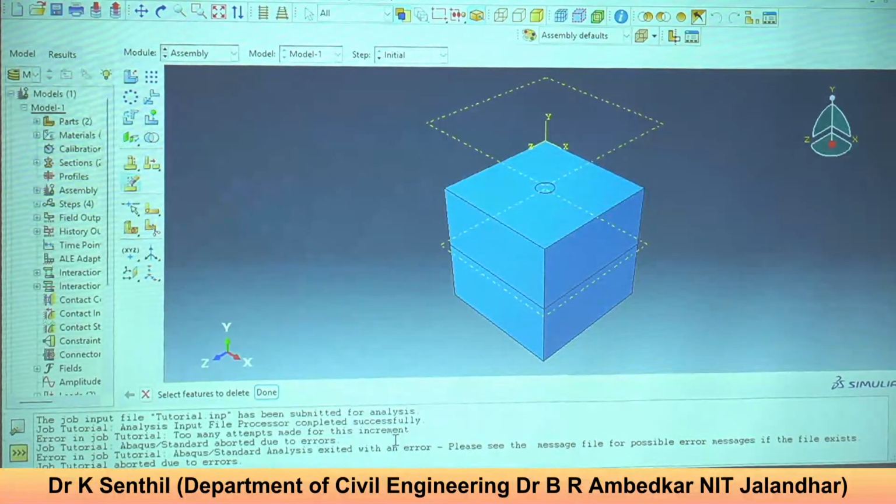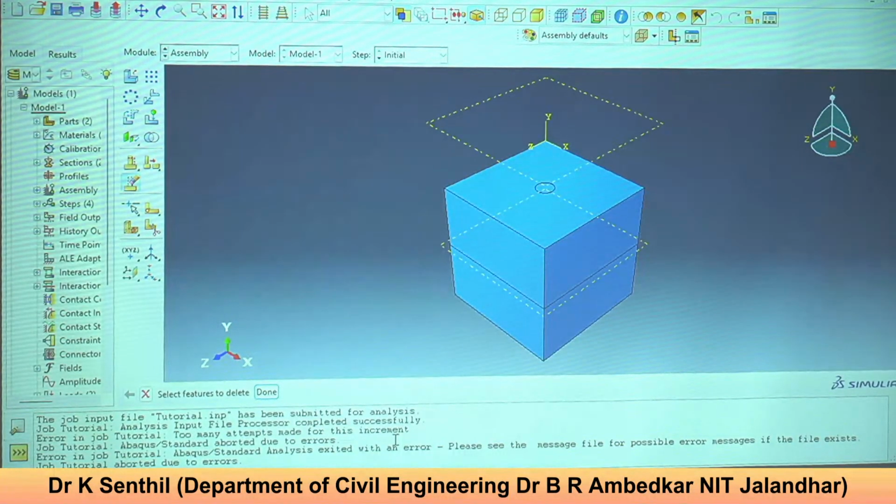If the loading is not applied gradually but occurs simultaneously at time t equal to 0, both gravity load and load on the pile acting together plus external load, maybe that is one reason, but I don't think that might be the reason. But let's try the ramp load, as he was suggesting. The ramp load is nothing but a load starting at 0 and increasing for every time step.